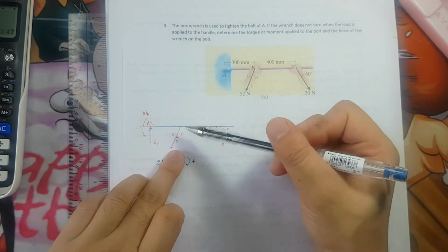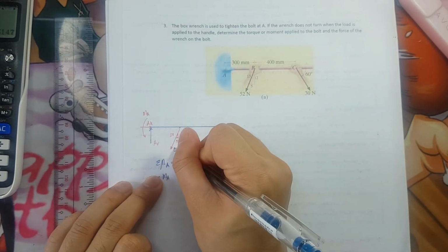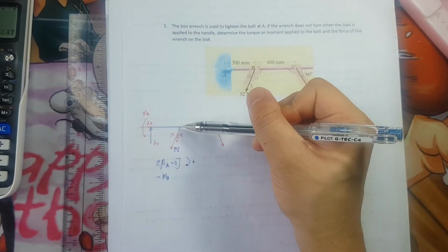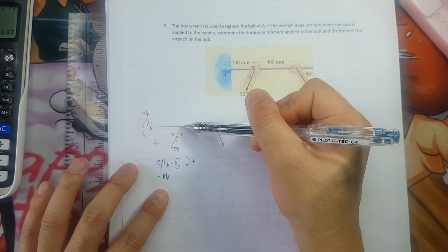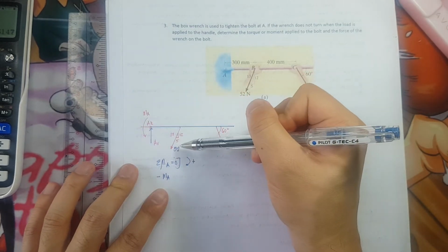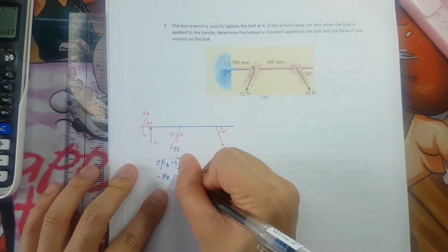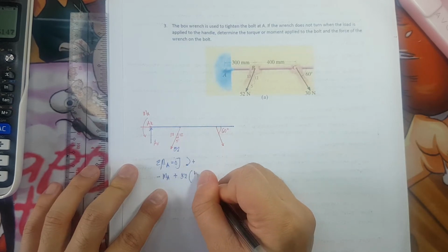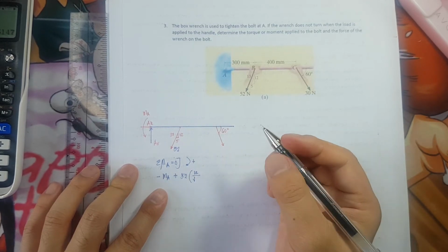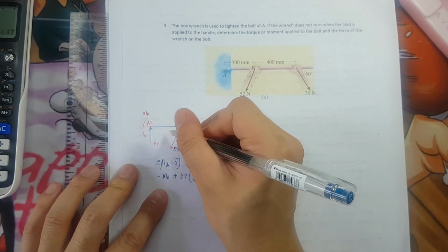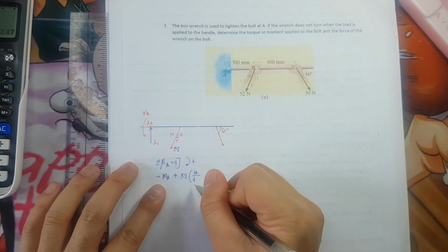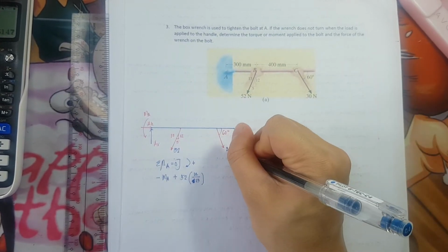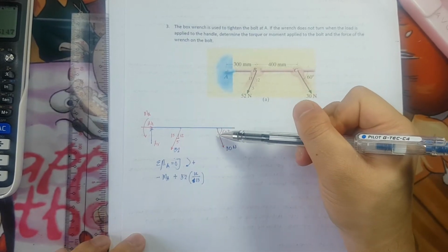Then we have here the 52 Newton force, and I will only consider the vertical because the horizontal is concurrent. The vertical component would be rotating in a clockwise manner, therefore it is positive. So plus 52 times the vertical component of the slope, which is 12, divided by the hypotenuse, which is 13. Next we have here the 30 Newton force, and the 30 Newton force is also rotating clockwise for